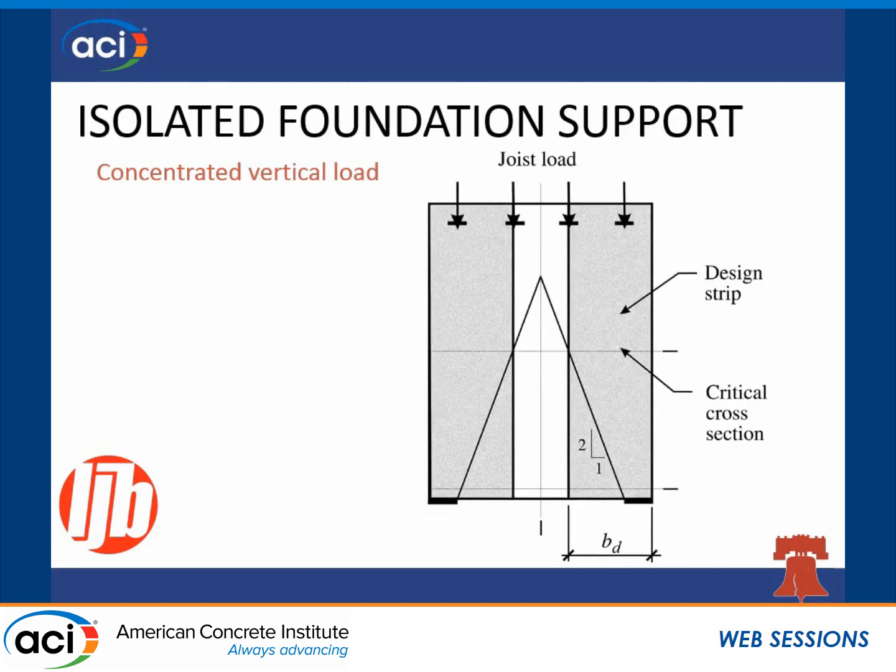We also commonly find this situation with concentrated vertical loads. A lot of times we're used to dealing with them from a building engineer perspective, where we have a high girder load or very high loads from the roof or from the floor beam. But this can happen when you have, again, panels on drilled piers or caissons or a pier cap or something where it's not a uniform load across the base of the panel.